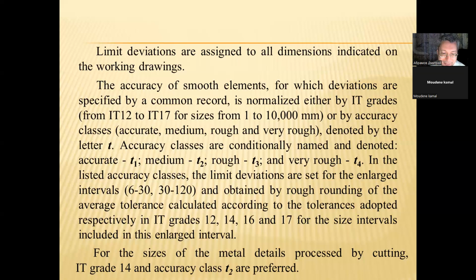For the sizes of metal details processed by cutting, IT grade 14 and accuracy class T suffix 2 are preferred.